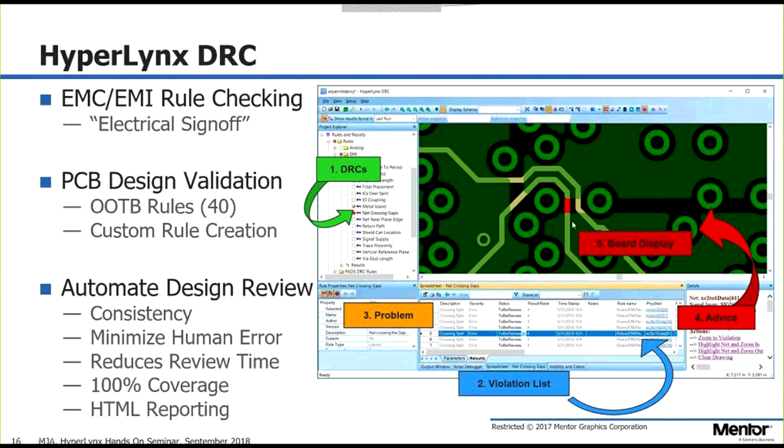basically they become antennas. You've got exposed copper here, radiation could come there, but then particularly on the return path, where you can imagine the power trying to pull back through here, it gets to this point trying to get that current flow in the opposite direction over this gap. It's basically just going to jump from here to there, which is essentially becoming an antenna. There are a number of different rules like that, where we can look for structures and see if there's something that's just routed in a way that's not going to work.